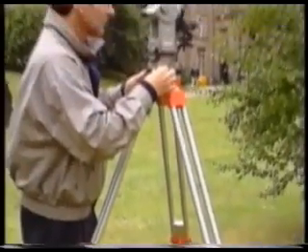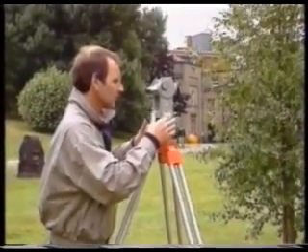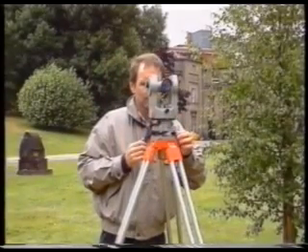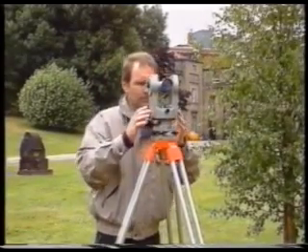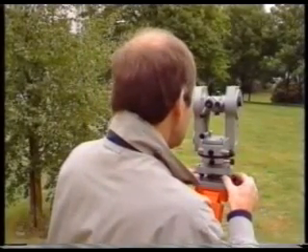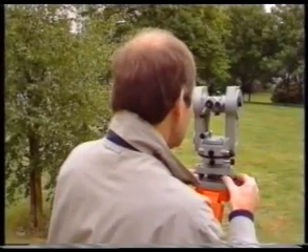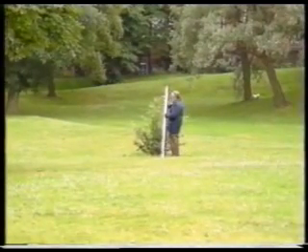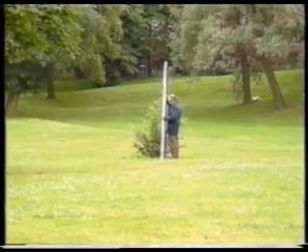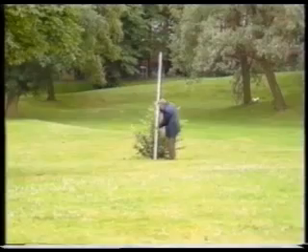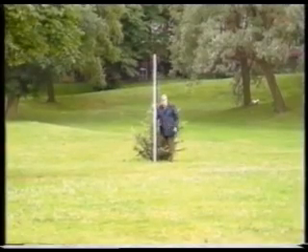Because of the widespread use of electromagnetic distance measuring instruments, only one ODM method is still generally in use. The reason that it has survived is due to the fact that it uses conventional surveying instruments. The technique is known as stadia tachyometry and involves the use of a theodolite and a leveling staff. Its main application is for the surveying of the positions of soft detail, such as trees, hedges, changes of slope, and so on, in order that they can be plotted on a plan.